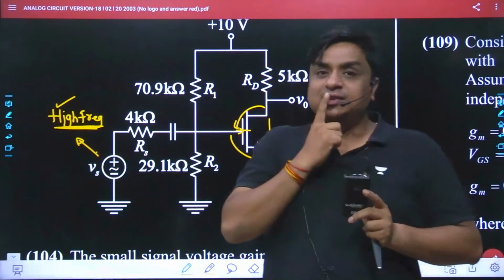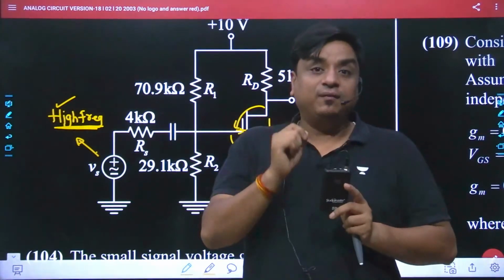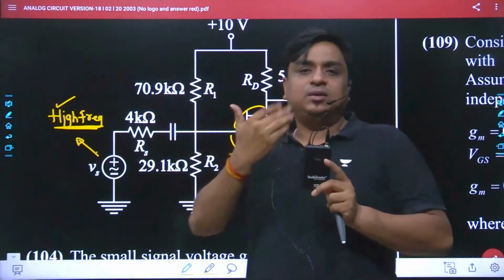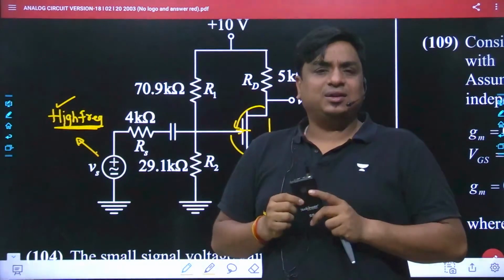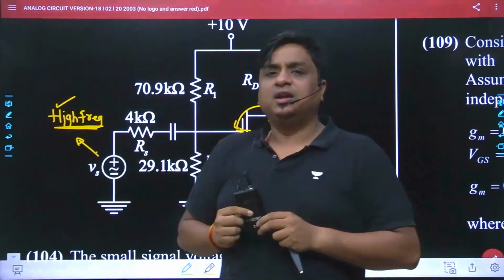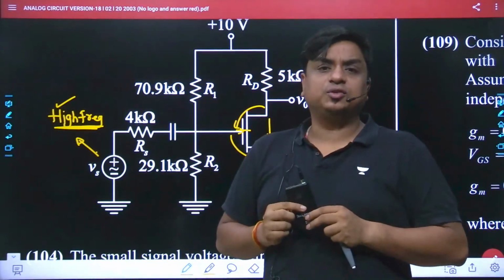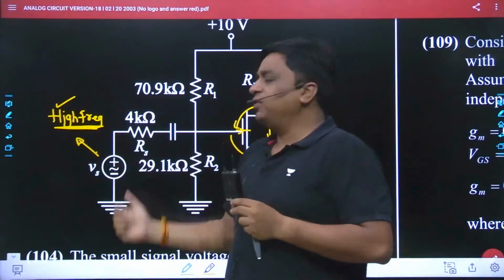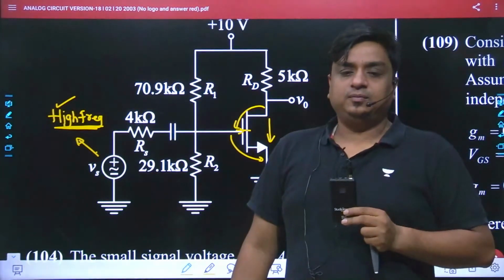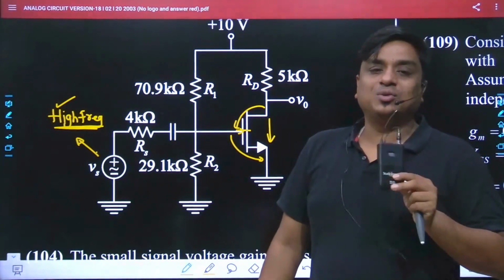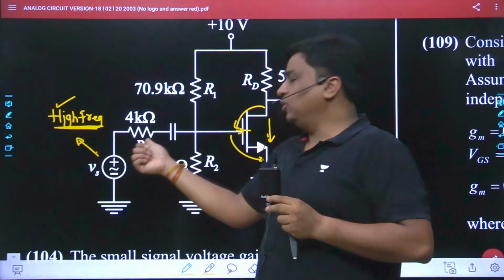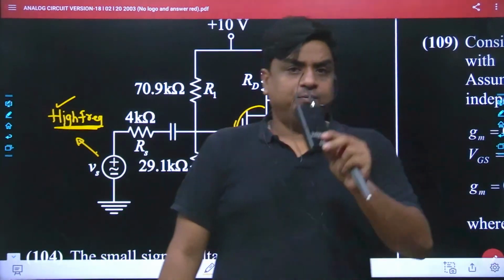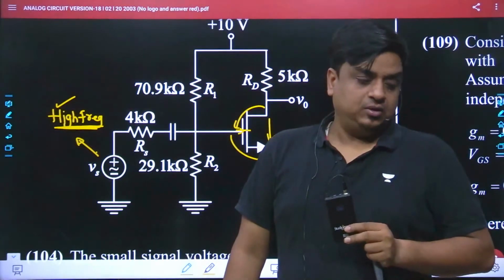Now whether my frequency is on a higher side or a lower side will decide the equivalent of this MOS. This is a vocal signal. Probably at maximum it will fall in the range of 5 kilohertz. You have seen that the human vocal signal cannot go more than 3 kilohertz. So obviously the input signal I have applied to this circuit is low in frequency. Did you really understand what I'm saying? Low in frequency. And as it is low in frequency, obviously I can simply say that for the MOS, all of the capacitive effects are neglected. Did you understand what exactly I wanted to communicate? Yes.